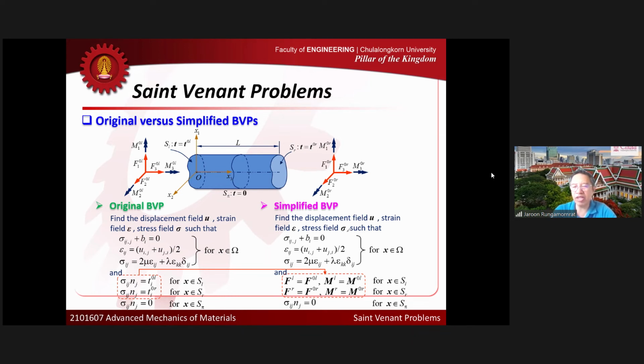Solving the governing equation is not an easy job, right? So I will try to avoid doing that in this class. I will try to apply the inverse technique, by guessing the form of the solution and verifying the satisfaction of the governing equation inside, and then checking the boundary condition. Similar to your homework assignment. Okay, I will use that kind of technique to get the solution here.